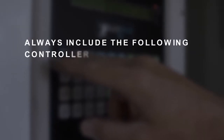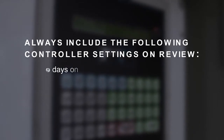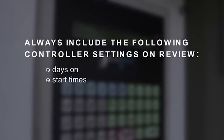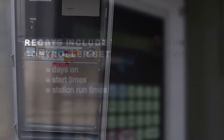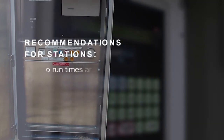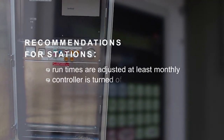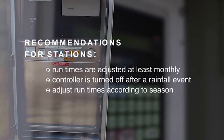This review of controller settings for each station should include reviewing days on, start times, and station run times. These settings should be checked for each program on the controller. It is recommended that the station run times are adjusted at least monthly and that the controller is turned off after a rainfall event. Summer months are when the irrigation demand is highest, and demand drops off during spring and autumn, so runtime should be adjusted accordingly.